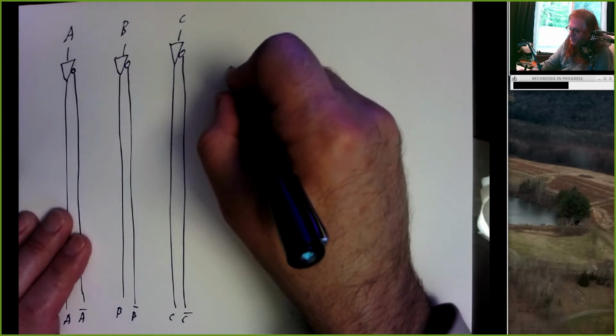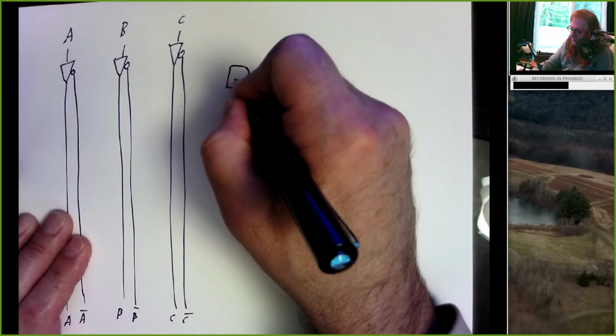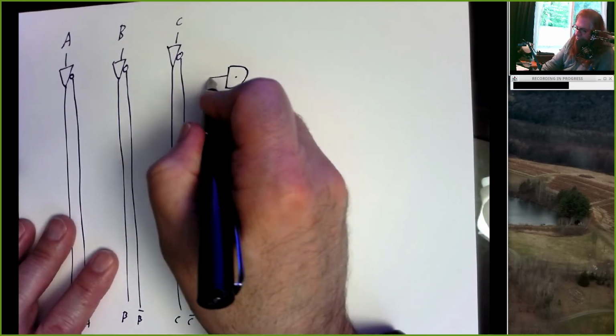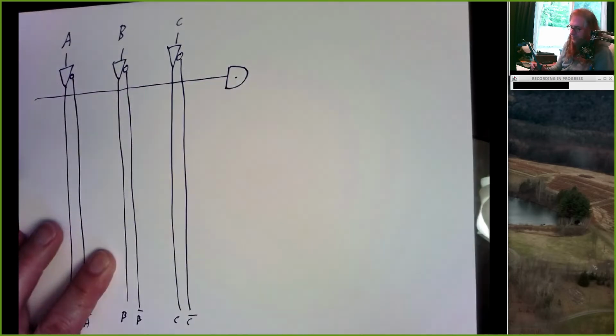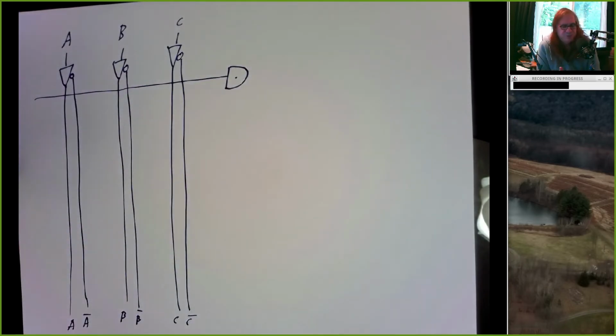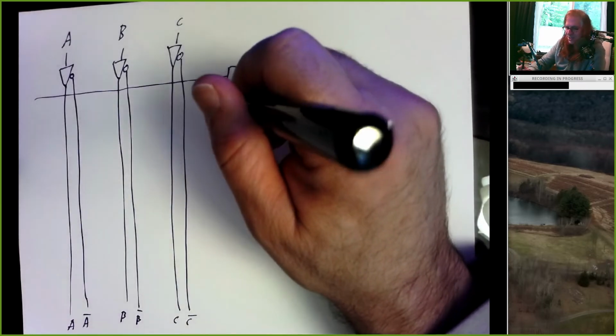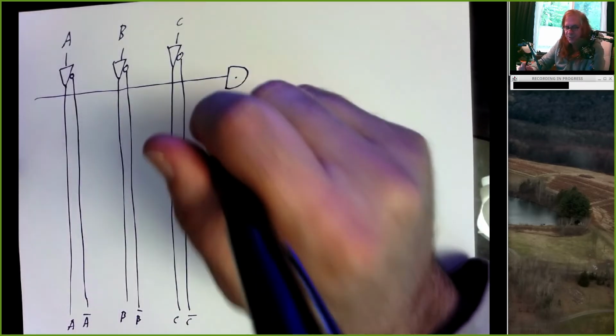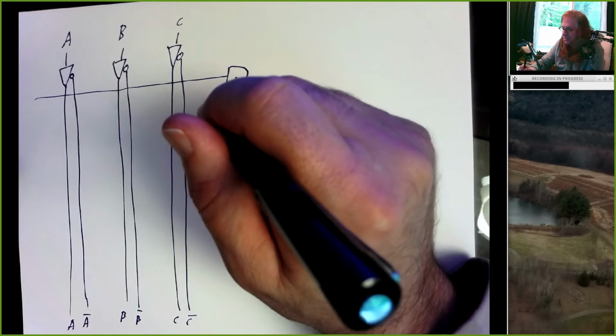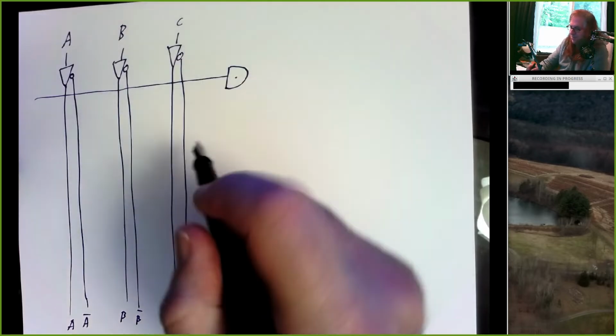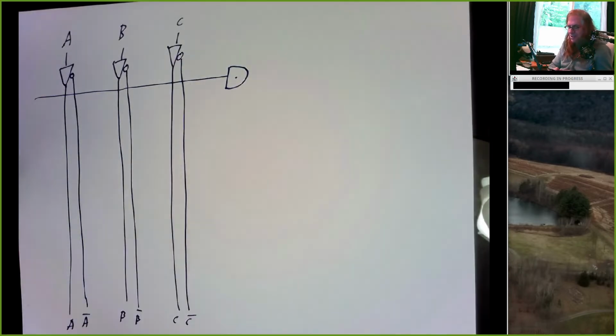And I'm going to draw an AND gate with a single line coming off. Now, there's really no such thing as a 1-input AND gate, because what would that do? If you put in a 0, you got 0, put in a 1, you got 1. This is not a physical device. It's a shorthand for when we're talking about programmable logic, which says, hey, I've got multiple inputs coming here, but suppose I want to do A and B and C bar.